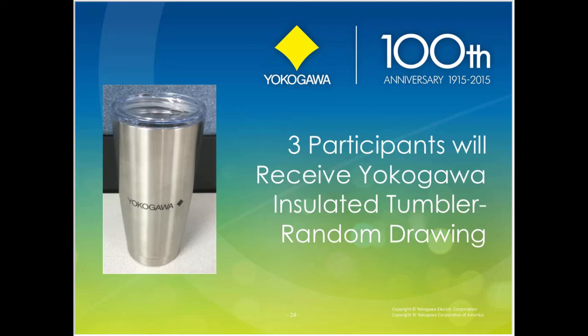Yeah, we have a quick pass-fail analysis, or we can do the full wake frequency calculation. The full wake frequency calculation will give you an official report that'll say pass or fail, along with any recommendations on how to modify the thermal well so that it will work in that application, whether it be shortening the length or making the base more stocky. So those are a couple of ways to address it.